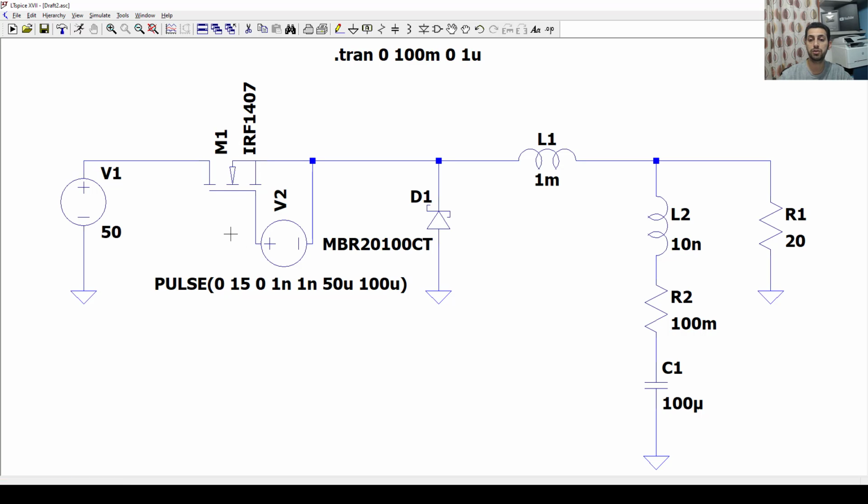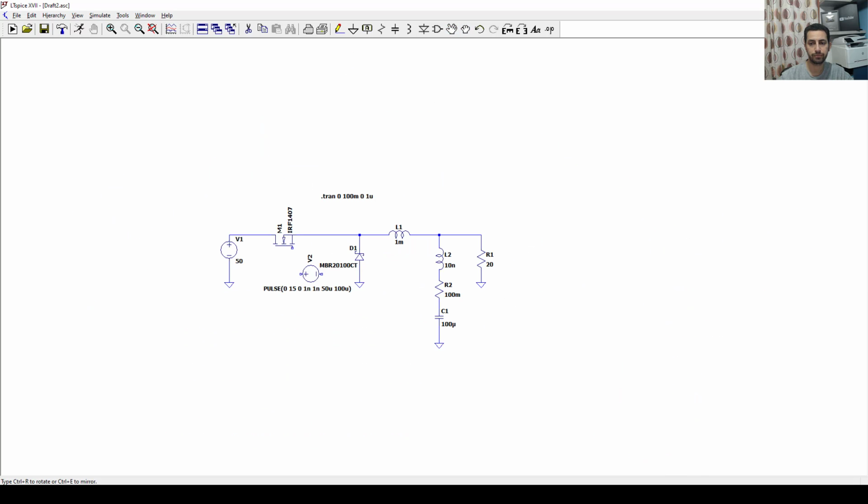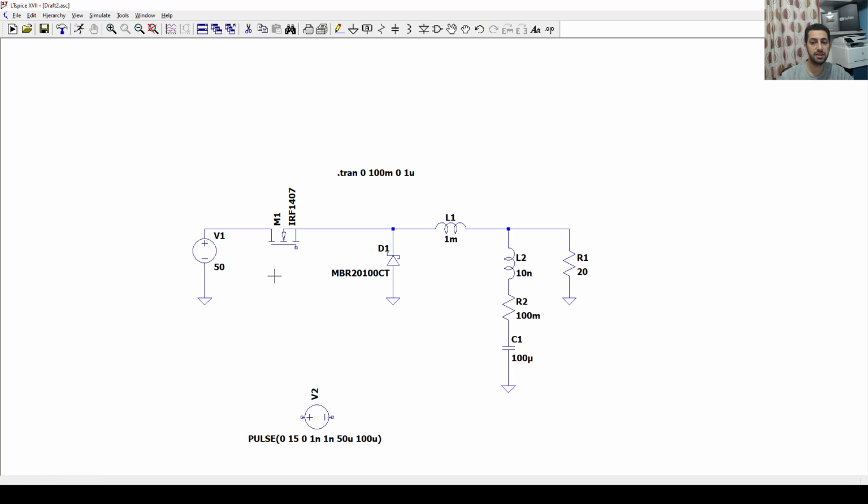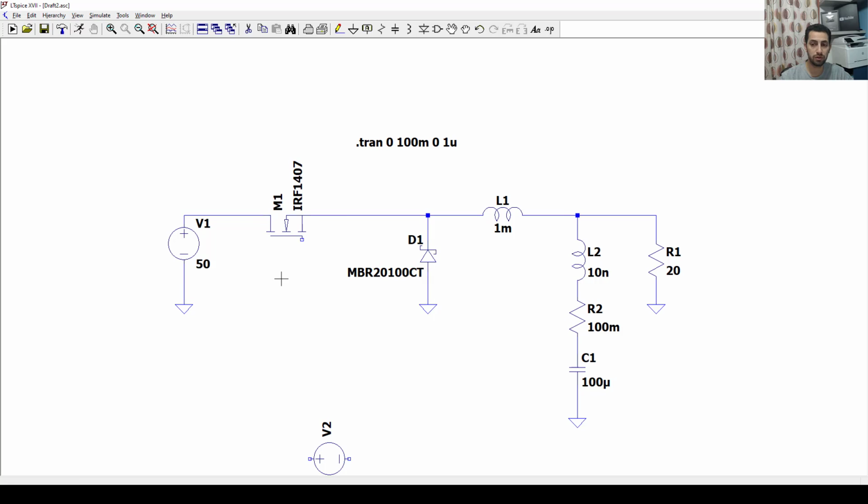So in this part we are going to see what approaches we have to make a high side driver for this MOSFET. The first thing we can think about is just to separate that generator, and we just move it somewhere. That MOSFET needs high voltage to turn on and low voltage to turn off. So I will use a resistor, and that resistor is supplied by that supply. So the input supply will also be supplying the gate, and I will see if that's correct or not.